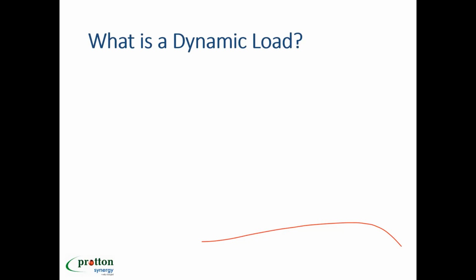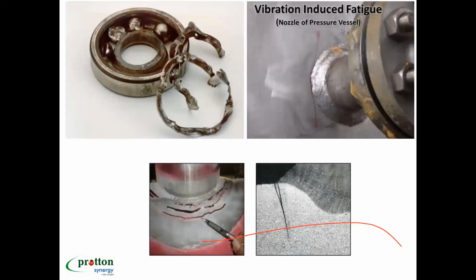So this is because we as stress engineers are not looking at the flow part of it. For us, dynamic analysis is nothing but modal analysis and just skipping a frequency of 4 hertz. Now sometimes it has become 5 hertz. And we are thinking, if I keep the frequency at 5 hertz, then I have done the dynamic analysis, which is not the truth. As we have seen, dynamic analysis is all about the failures which you would be addressing because of the bearing failure, or some kind of cracks getting developed in the system.